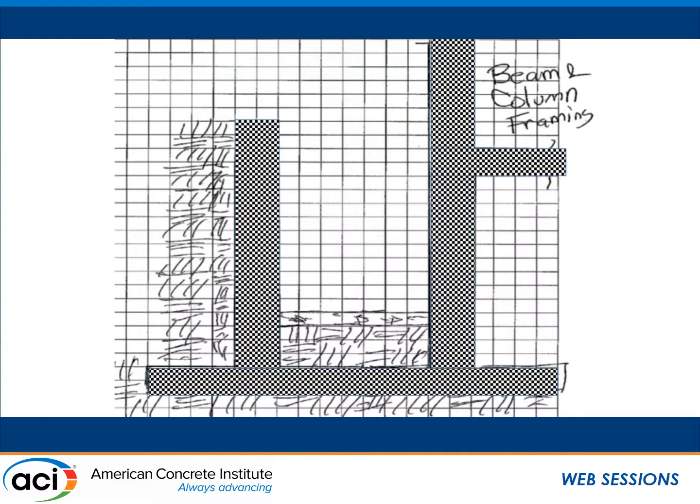This was another interesting one. We've got this wall right here, and the question is, what are we going to do with this wall? Well, the architect decided he wanted to put his curtain wall on top of that retaining wall after it was backfilled, and he had a magical dimension in all the framing coming off of this framing over here. So obviously, when the wall got backfilled, all of a sudden things got interesting because it moved a little bit, and the curtain wall guy wasn't happy with everybody.